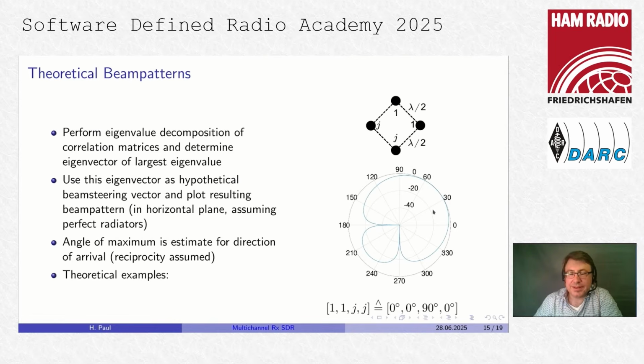What you now get is a propagation into 45 degrees, into this direction here. Because you have the phase shift, for instance into this direction the signals cancel perfectly, and also in this direction the signals cancel perfectly, and there's absolutely no radiated signal into these two directions because of the way you feed the antennas here.